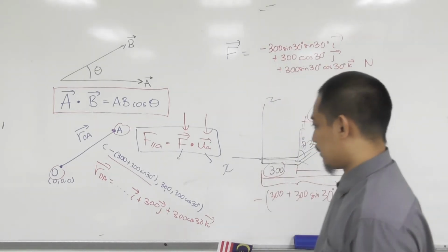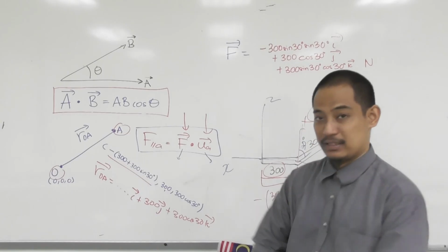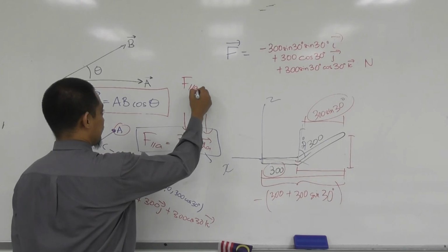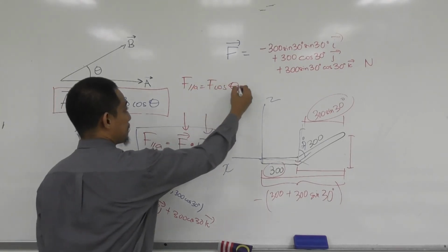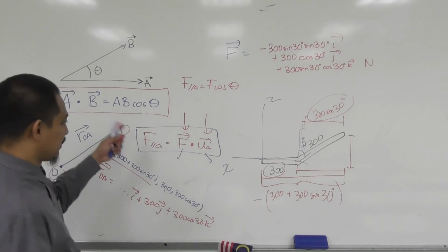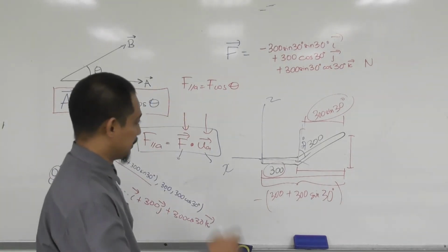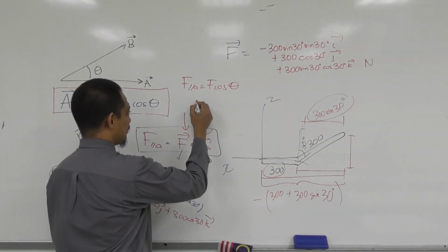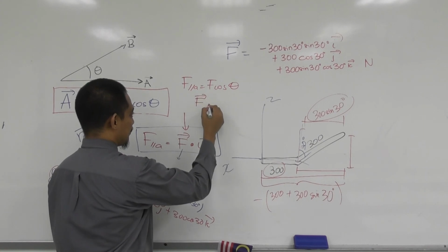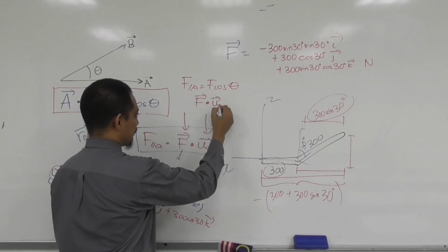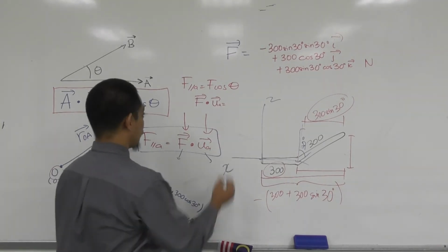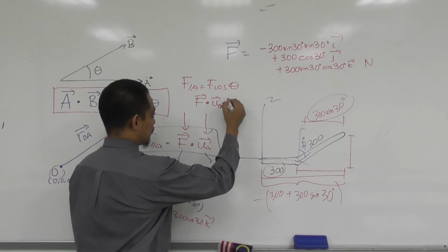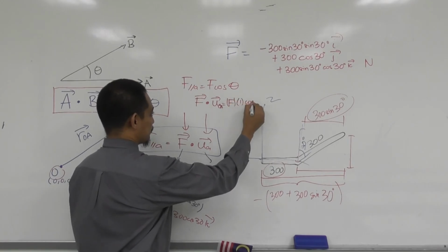Now, in the slide, they actually show both ways. Meaning I'm using this one straight away, but there's another way where you use F parallel A is F cos theta. However, you don't have theta in this question, right? So they use dot product actually to get theta. They use F dot the unit vector of OA, which becomes force times 1 times cos theta.